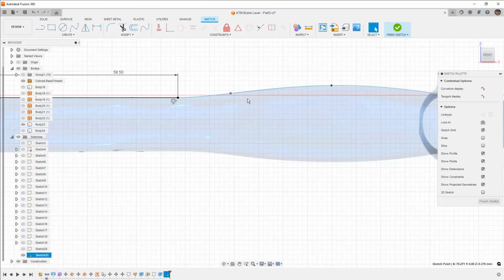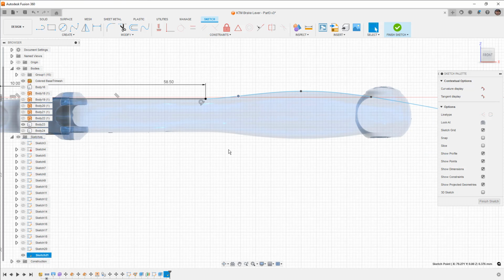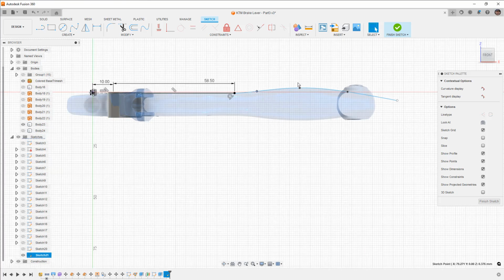And when we're thinking about machining to a flat surface, tangency is really all we're going to get out of this. It's not like we're making a complex injection mold or anything like that. So taking a tool, let's say a ball end mill or bullnose mill across this and then up, that tangency is going to be essentially all we need in order to get that transition. Now, if you go to a G2 continuity, the smooth or curvature constraint, it's not really going to buy you too much because we're dealing with a flat plane ramping up in 3D.